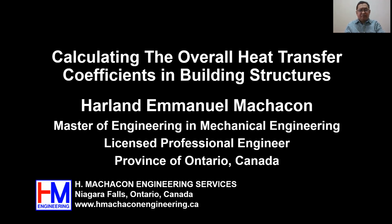Today, our topic will be calculating the overall heat transfer coefficients in building structures. We need the value of the overall heat transfer coefficient in a building structure so that we will be able to calculate the heat loss in a building, and therefore we will be able to properly size the heating, ventilating, and air conditioning equipment.